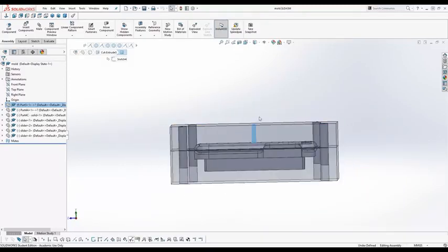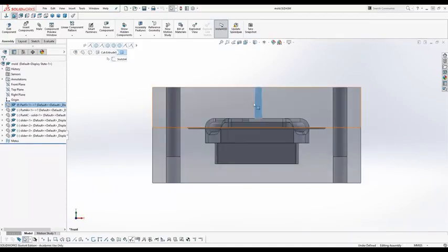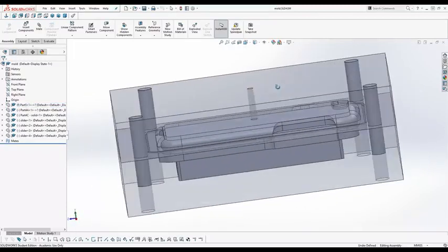As you can see, I didn't model the connector for the mold, so it can be connected to the injection machine straight away. This is because it would add a lot of cost to the mold. They would need to face off a lot of material, and the screw connector would be made from aluminium in the end. To solve this, I made a connector from some sheet metal and a plumbing end that can be screwed on the mold itself, and then it can still be used with the normal injection machine. Now the mold is basically ready to be produced.